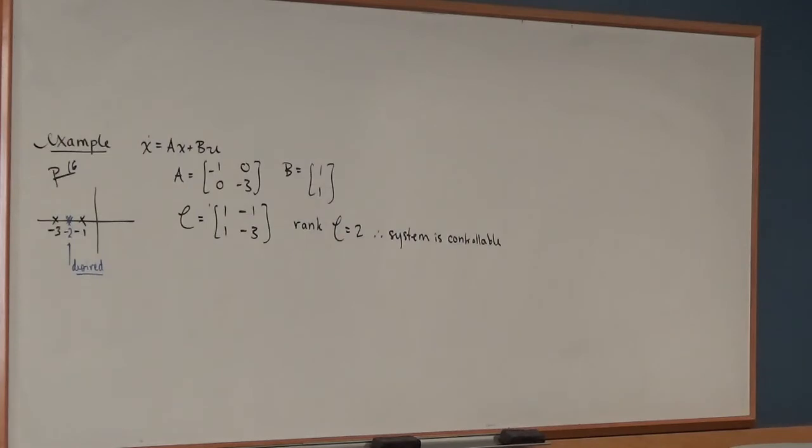I first transformed the system to controllable canonical form. And then once it's in controllable canonical form, it's almost by inspection how you design that matrix F. And then I transformed it back. So that's about 3 pages if you follow the notes.